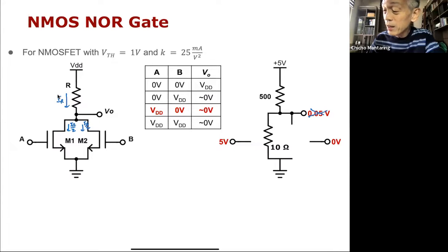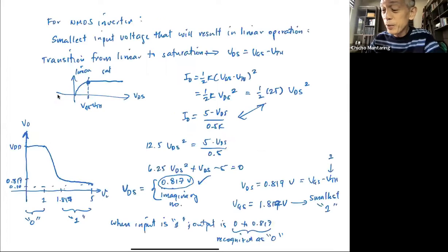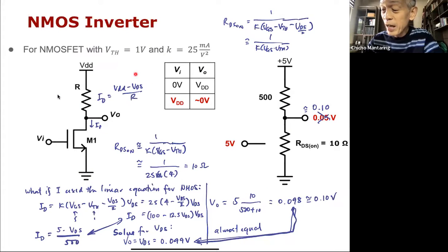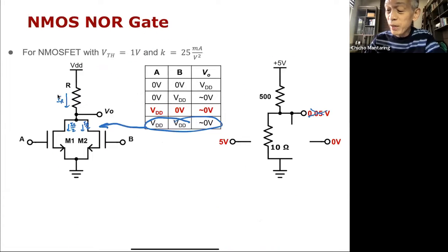For this particular input combination. No? So yung formula mo dito will not be like this, no? You have to divide this by 2 because it's going to be shared by these two transistors. Although if you want to simplify matters, you can just use the RDS on approximation. So this is using the RDS on approximation.